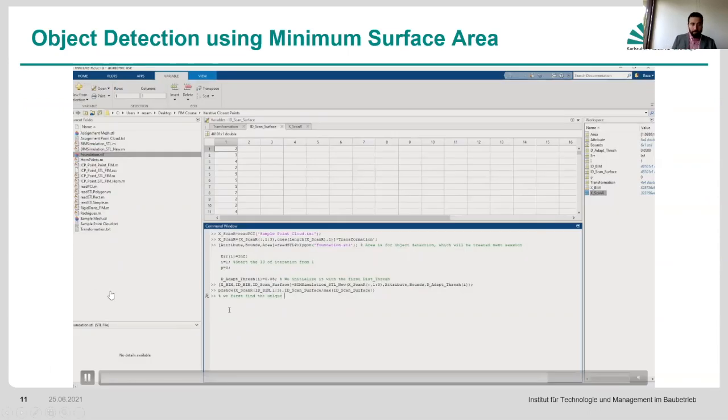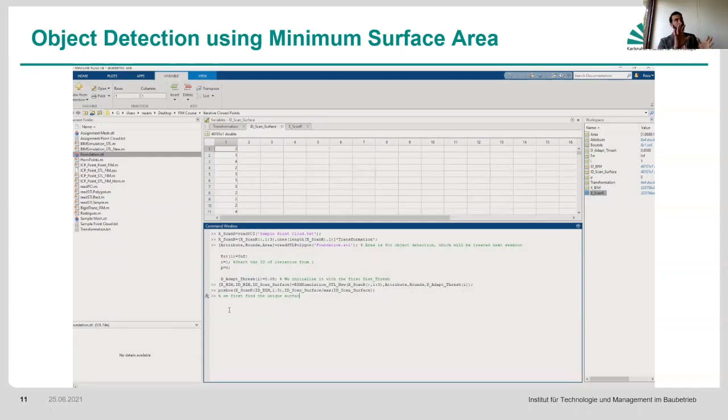So we first find the unique IDs. The reason why we're doing the unique is that there are surfaces dependent upon the point cloud. Imagine that you have only one side of a particular column, only these two that you're monitoring. If you look at it in the other algorithm for the ICP, there's not going to be any other points that would be projected onto the other two surfaces, right?